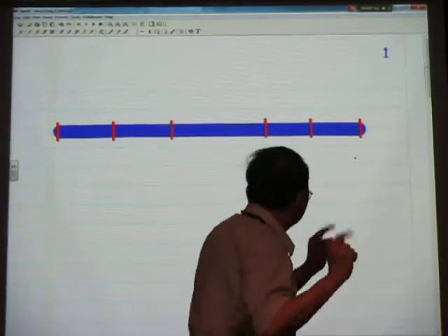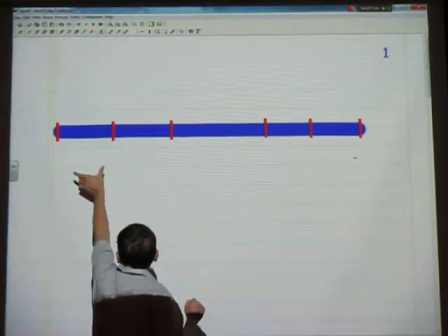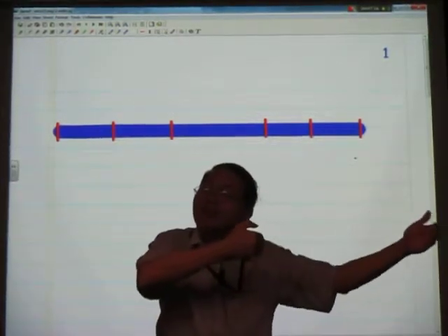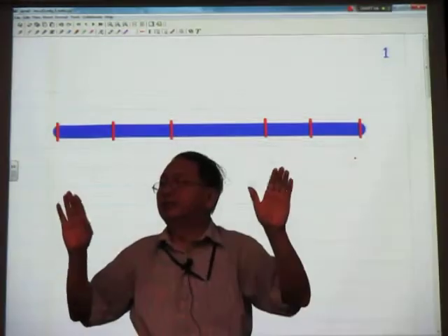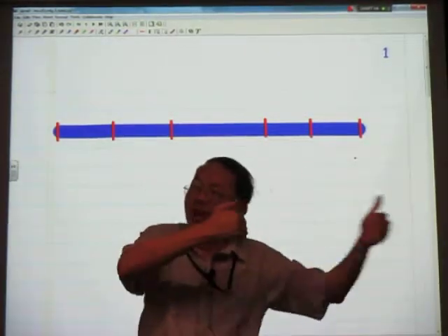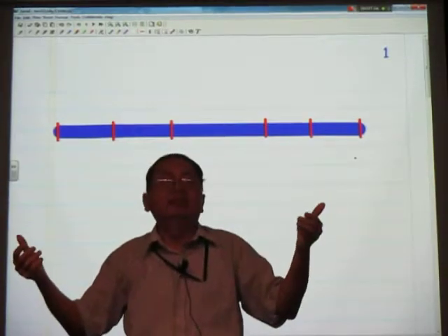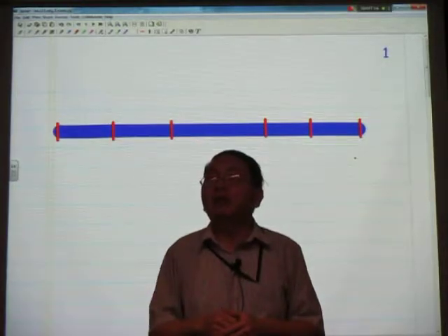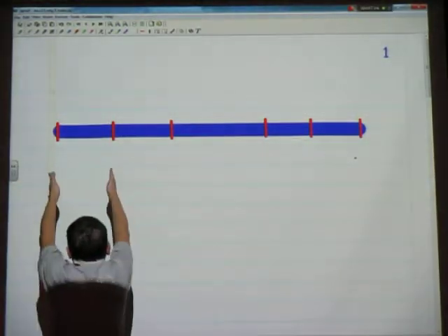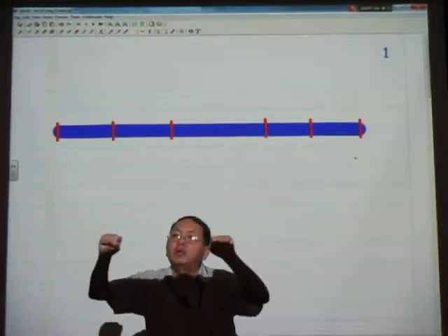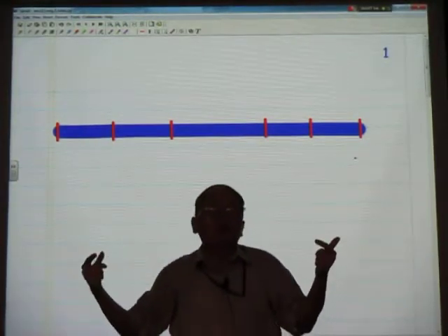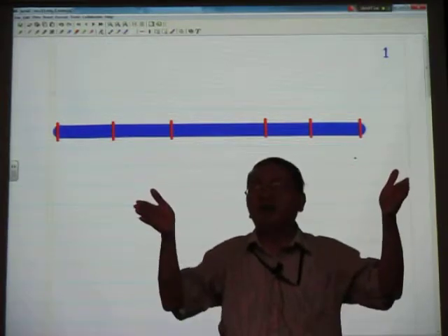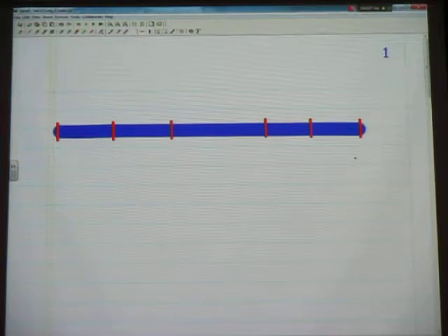Okay, so each of these elements here works only in the axial direction. Just consider the deformation in the axial direction, like an elastic bar. Okay, and when you formulate the finite element model, each element here can be represented by a spring. And there's a spring constant that is related to the Young's modulus, the area of the cross section, and the length of the element. Okay, maybe let me just write it down here.